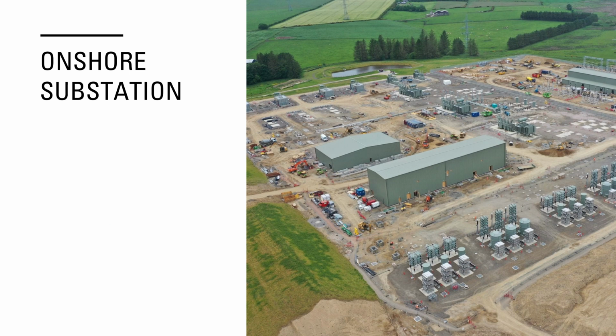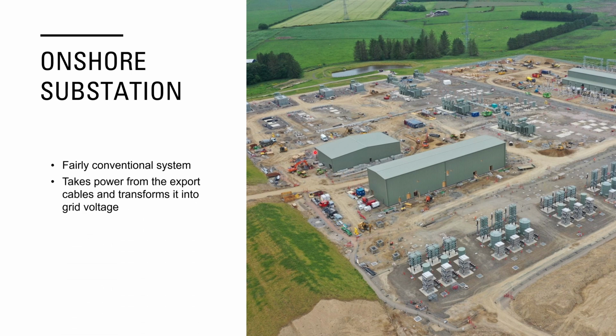The onshore substation is maybe a little bit less interesting. It's a fairly conventional system. Here's one being built in the north of Scotland for a 1 gigawatt offshore wind farm. You can see it's quite a large unit, but it's not particularly challenging generally. Its job is to take power from the export cables and transform it and condition it into the grid. Now that transforming is fairly straightforward, but the conditioning means dealing with harmonics and reactive power, and that can take up more equipment and more space and more complexity.